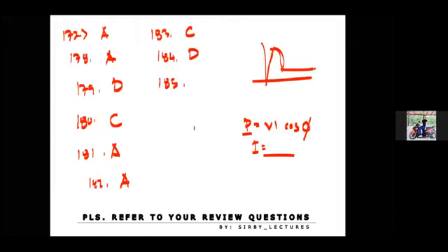So the answer here is that if there's a loose connection in the overload relay, that's also probably possible, or it won't provide any power. Okay, so that's one answer.